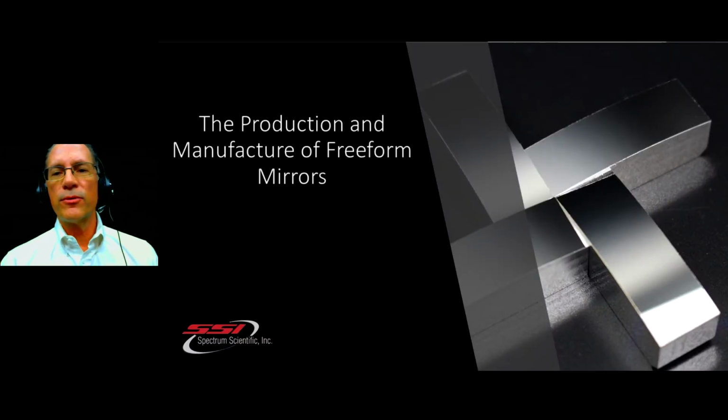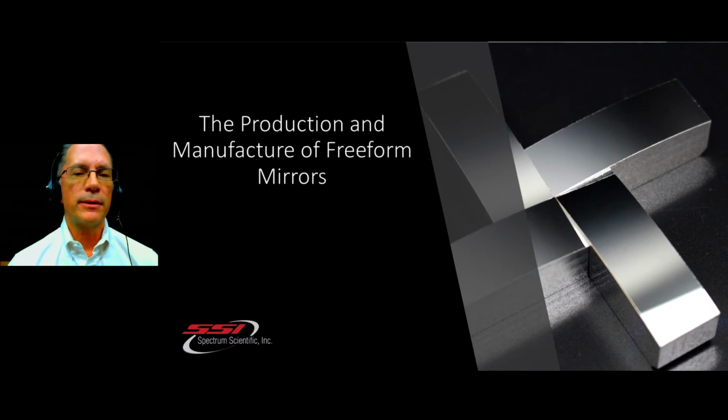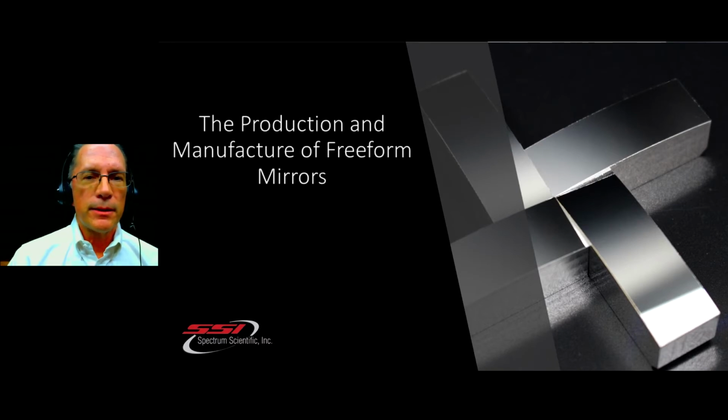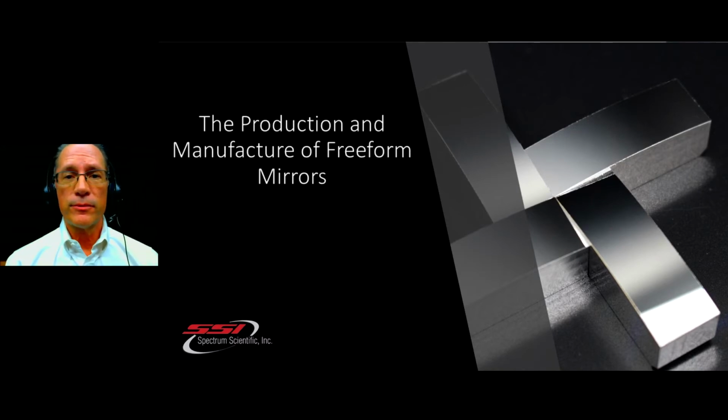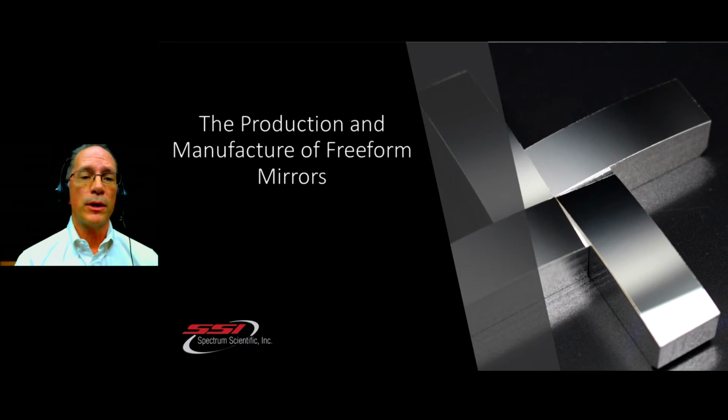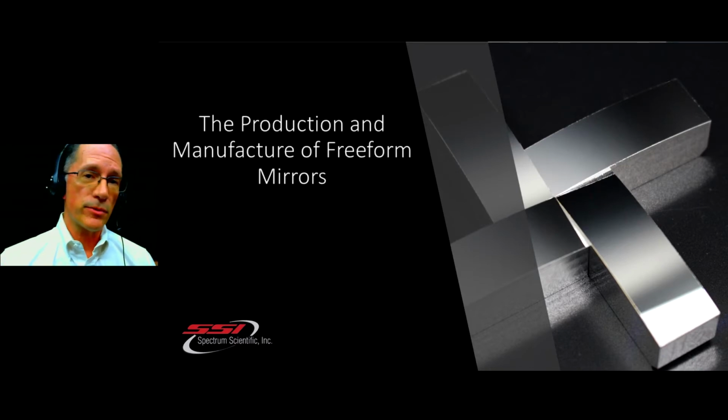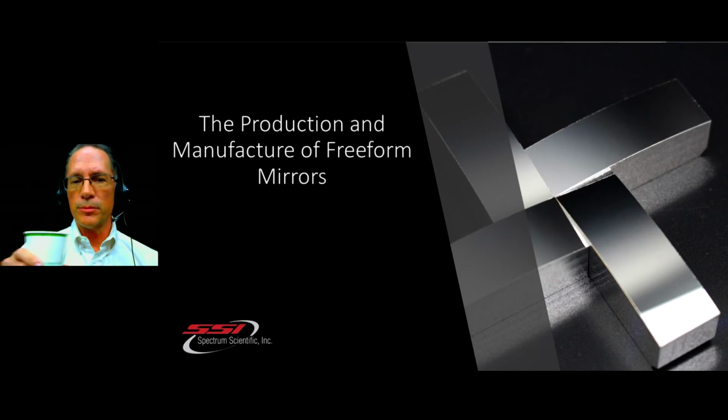Oh yes, freeform mirrors. This is a hot topic lately, and it makes sense because it really is the next evolution of optics. A-spheres have been made now for several decades, and those have been well applied, well understood. Freeforms are the next evolution because you can combine two corrective surfaces into one. There's actually even more advantages other than just that with the freeforms. I think we touch on that a couple slides from now.